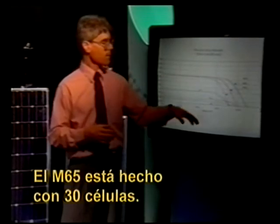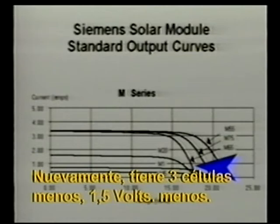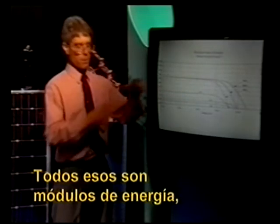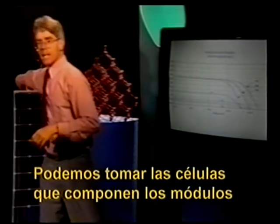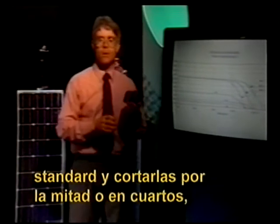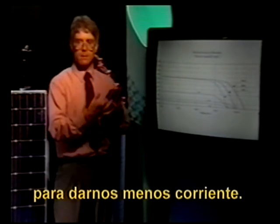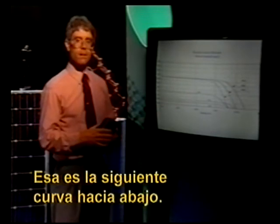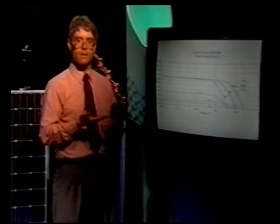The M65 is made with 30 cells. So there again, it's got 3 less cells, 1.5 less volts. All of those modules are what we call power modules. They're made with full-size cells. We can actually take the cells that make up the standard modules and cut them in half or quarter to give us less current. We do that on the M20. That's the next curve down. There, we've taken the standard cell and we've cut it in half.